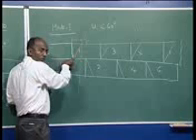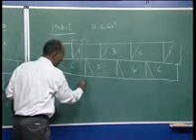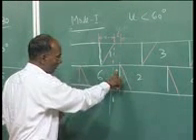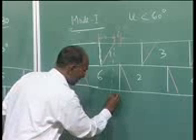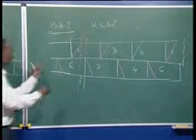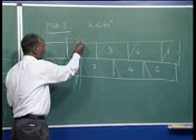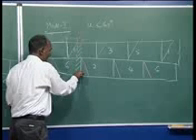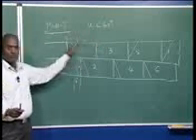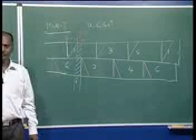So if we start here, 1 is there, then 6 is there, so I can write 6 1 conducting, no 2, because 6 is conducting in this portion. In this zone, 1 is there, because 1 is conducting here, and 6 is there, so 6 1 is conducting.